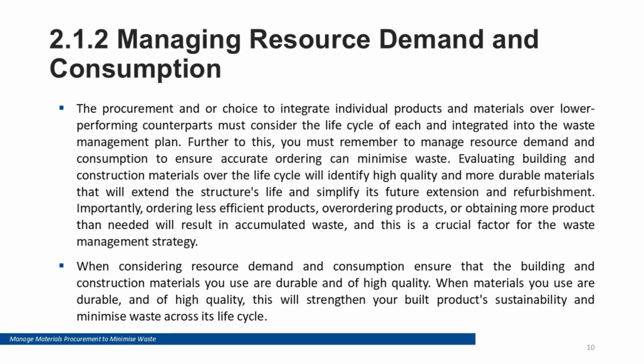Managing resource demand starts with accurate quantities and controlled use on site. Over-ordering and poor storage create waste quickly through damage, weather exposure, or loss. Use consistent estimating methods, confirm measurements, and align orders to the construction program so materials arrive when needed and can be stored safely. Track usage against budget and forecasts, so variances are identified early and corrective action prevents unnecessary waste.